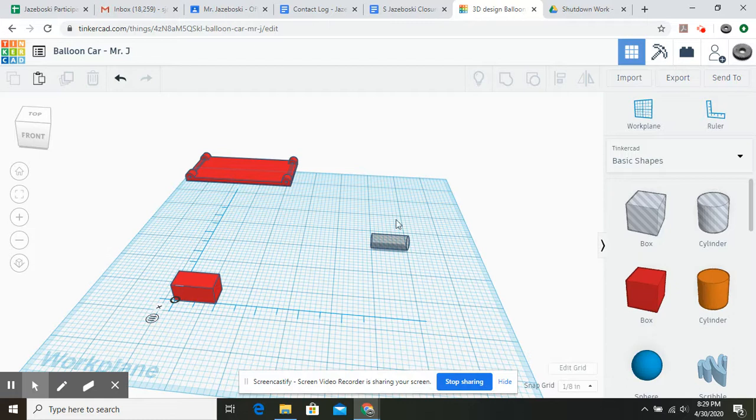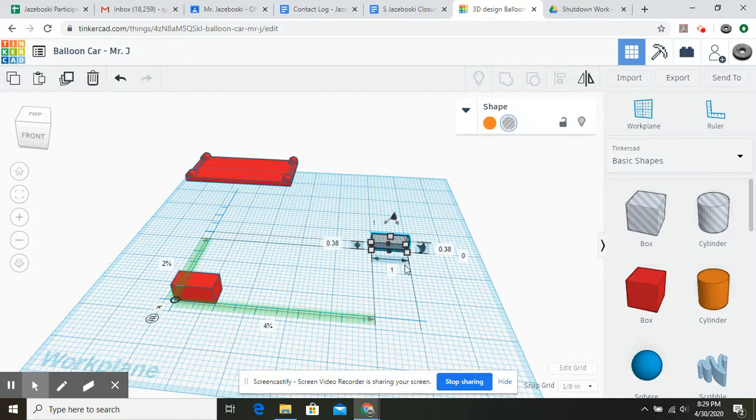With that, you want to make sure the part is aligned like that, because when we line it up, it has to go into this block to create a space for the tube that we're going to be using. Once that's done, we're going to raise the z-axis up.